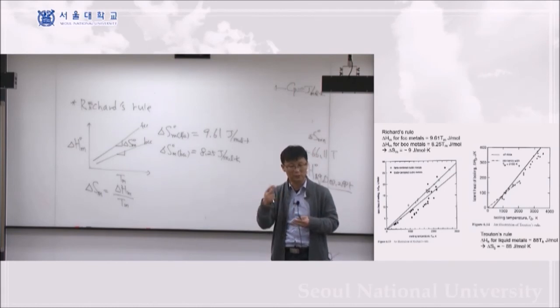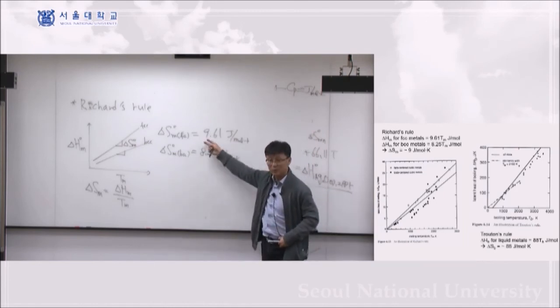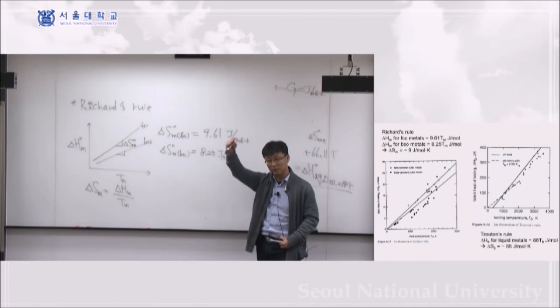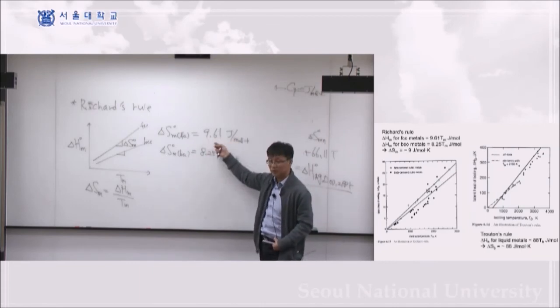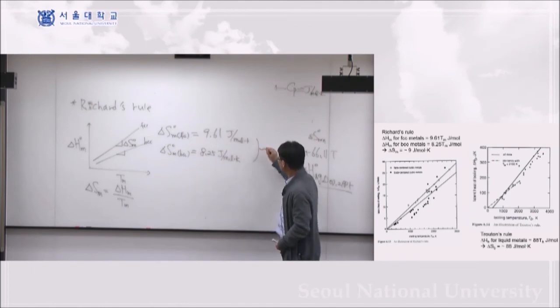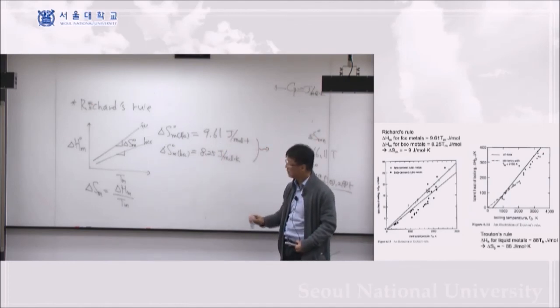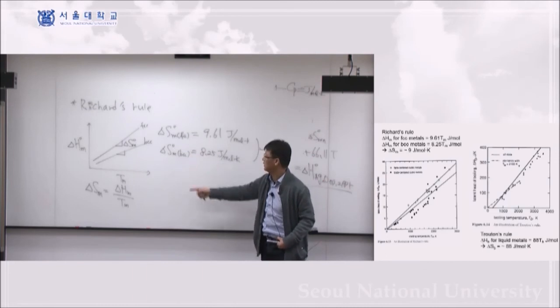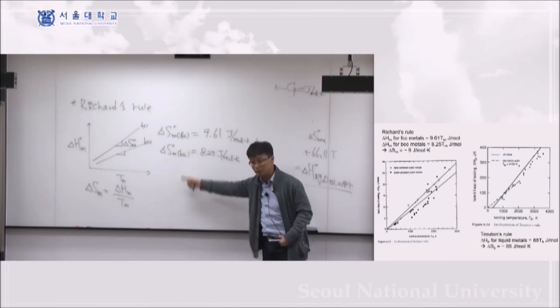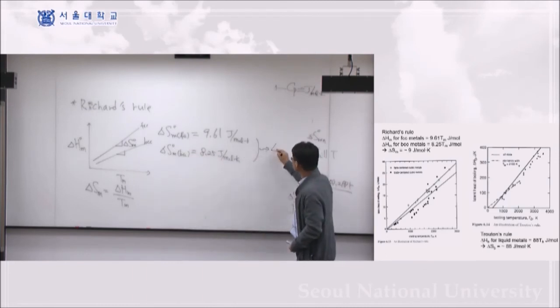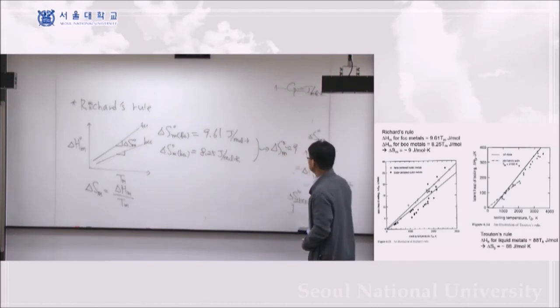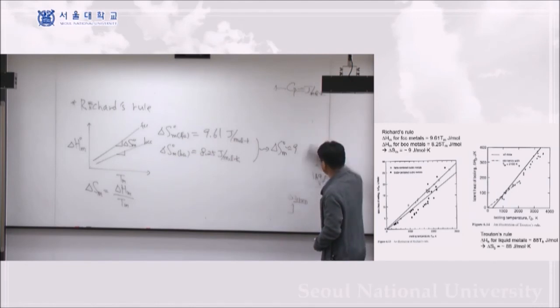Of course, enthalpy and entropy change with temperature, but at the melting temperature, we can see that when solid becomes liquid phase, it has a more or less constant value. If you look at this, solid becoming liquid phase, whether FCC, BCC, even HCP, all those kinds of material, delta S of melting is roughly about 9, or about 10 if you like. Okay.